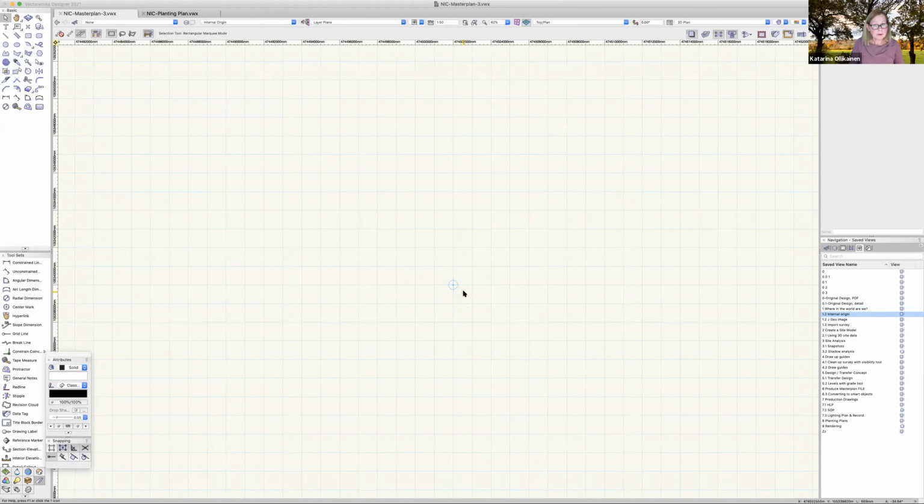For any CAD program to work and function properly, and it's not only Vectorworks, it's all different CAD programs, you have to stay within a radius of approximately 5 kilometers from this mark. Not even a speck of dust can be further away in your drawing. If you step outside this area, you will have a whole herd of problems. You will have strange geometry, things will be moving around, and the file will run like treacle. Not very nice at all.